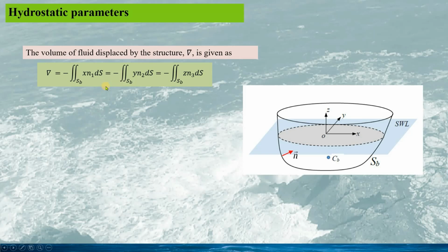Such information can be very useful in wave structure interaction analysis, when we need to check whether all the generated panels are oriented correctly. If all panels are oriented correctly, these three volumes should be very close if not identical.